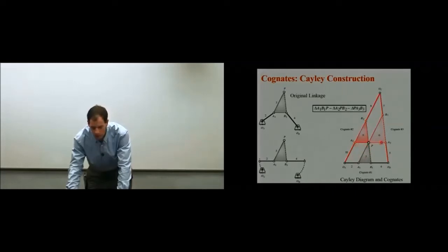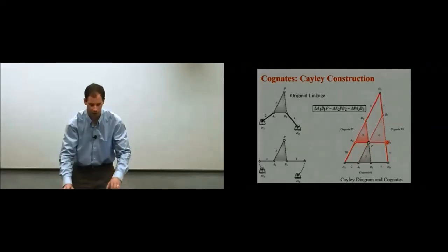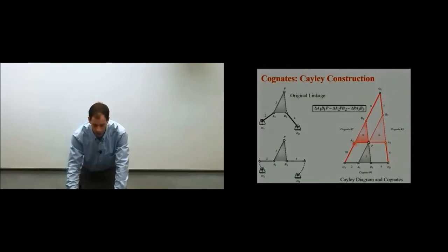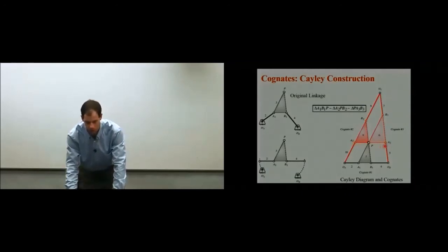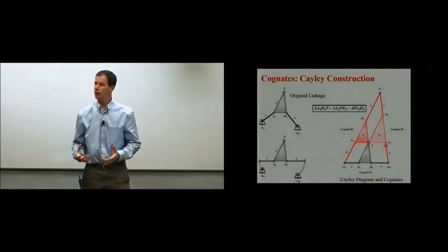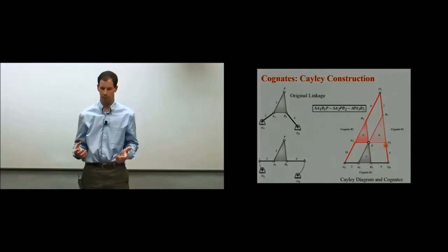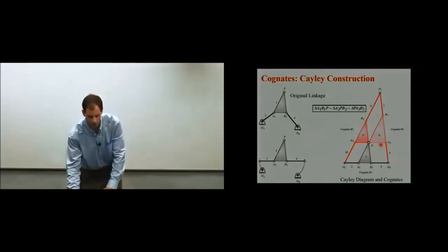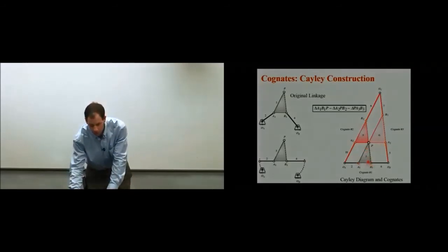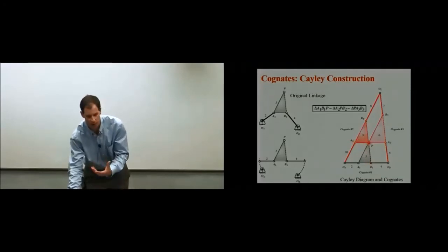And then just due to the fact that I've straightened all this out and made it a straight line, I've got a straight line from what I'm calling A2 to the precision point to A3. So all those are a straight line. And then I create 2 new couplers, which are similar triangles to the original coupler. So I just take the original coupler and I move it up here, and I've already got one side of it defined, so that defines the scale of this.